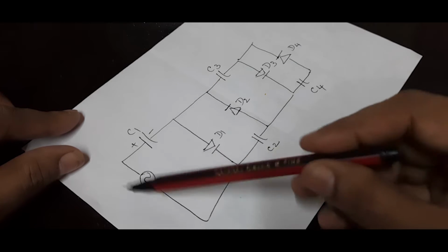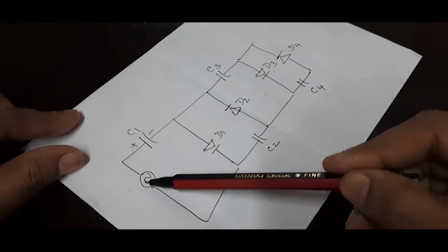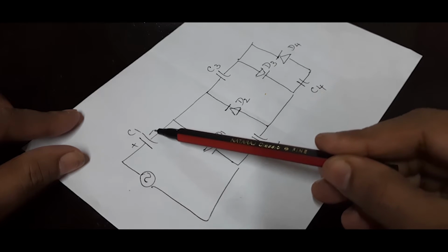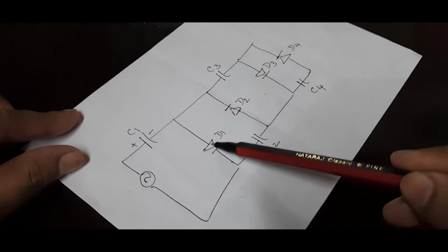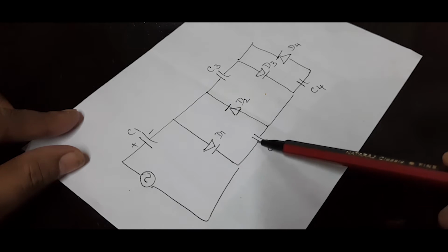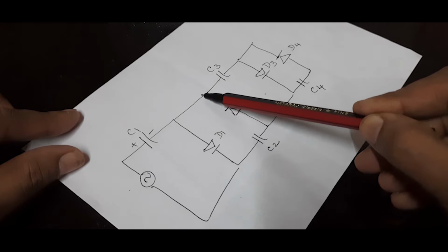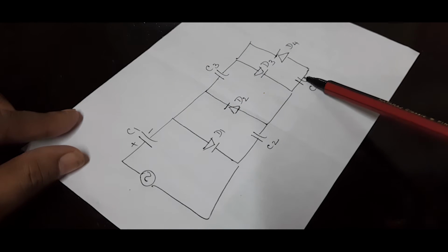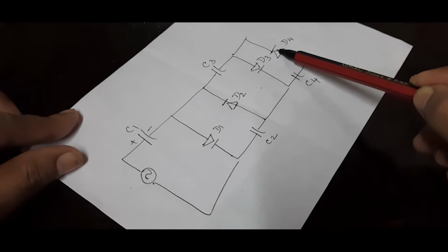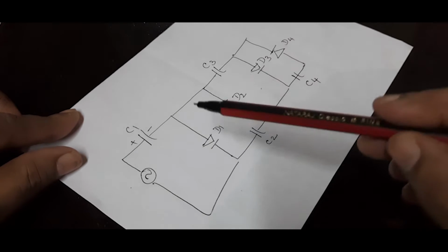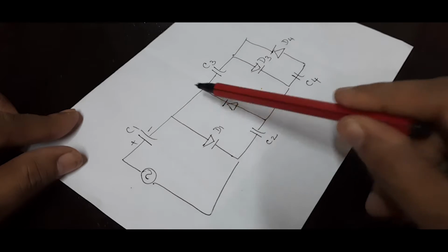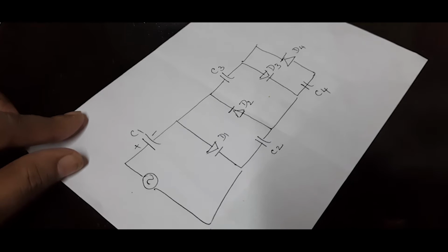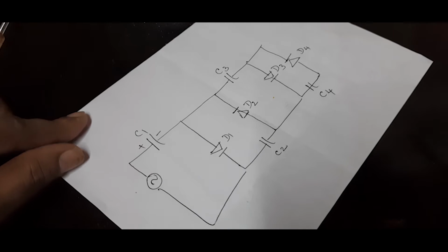So once again I'll follow the path for you. Signal generator or the signal, C1 capacitor positive, negative, diode positive, negative, capacitor positive, negative, diode positive, negative, capacitor positive, negative, diode positive, negative, capacitor positive, negative, diode positive, negative. So the circuit you just need to complete with direct connections to look like this. So this would be your simple voltage multiplier.